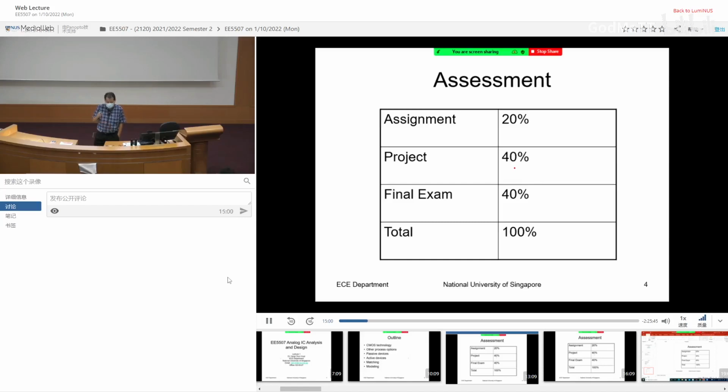Some of you might be thinking, this is straightforward, you have done that. But there are a few things that we add in. Because we are using the PDK, we can now run process corners. So you need to know how to run process corners. So with different transistor processes, how would the performance be affected?